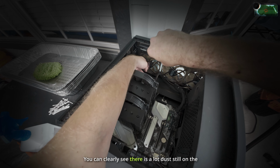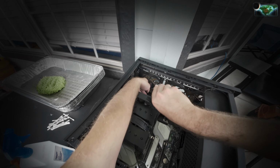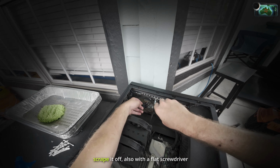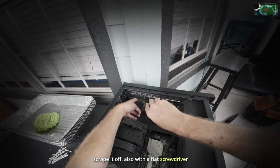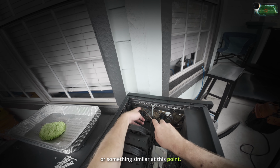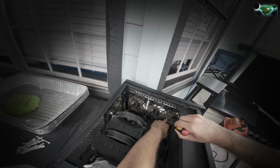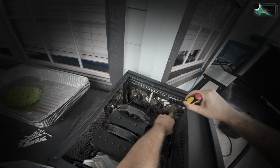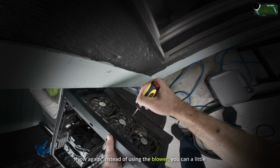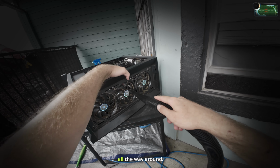You can clearly see there's a lot of dust still on the blades. It's not coming off. So what you can do is try to partially scrape it off, also with a flat screwdriver or something similar at this point. Now again, instead of using the blower, you can vacuum the leftovers a little bit all the way around.